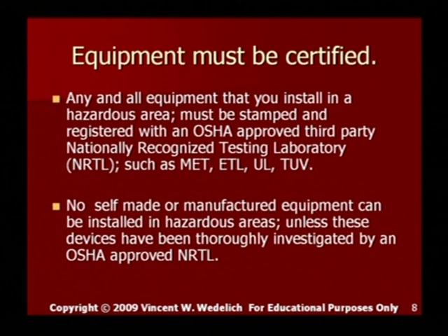Any and all equipment that you do install in a hazardous area must be stamped and registered with an OSHA-approved third-party nationally recognized testing laboratory such as MET, ETL, UL, TUV. No self-made or manufactured equipment can be installed in hazardous areas unless these devices have been thoroughly investigated by an OSHA-approved NRTL.